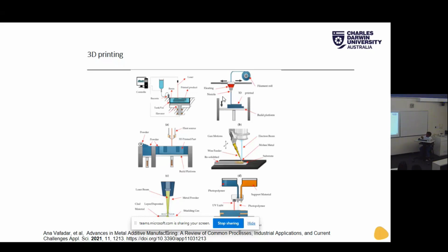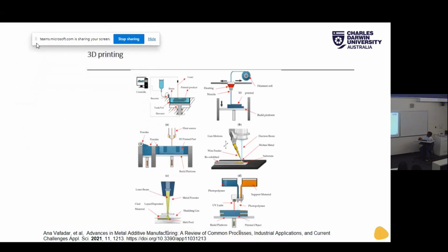So the one thing that I'm really keen to talk about in terms of the usage in the industry, I can't see. Can you see this carefully? Oh, that's a laser beam. Cool. So you have a laser beam on which powder is laid on a bed. And then the laser beam goes as dictated by the shape in a CAD file, and it melts the powder. And when the powder is melted, the powders fuse together, and they all join together.